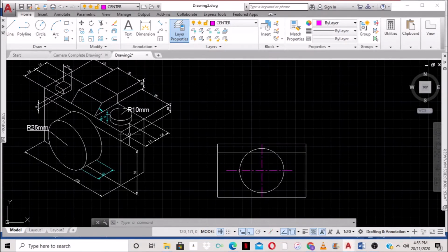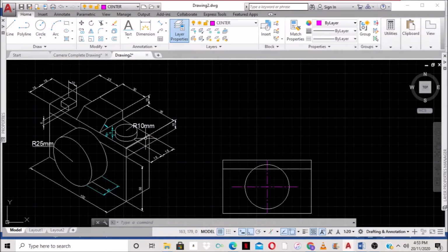Now I need this button here, the lens here, and also this button here. So I'm going to draw the lens first. So the lens now, as you can see, it is saying that from here to here it is 35. So to the start of the lens is 35, and then it is going 30. So if I divide this lens by 2, which is 15, I'm going to get 50. So therefore, if I come here, that's the center of my rectangle, which should be 50.